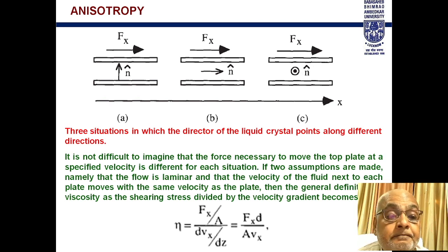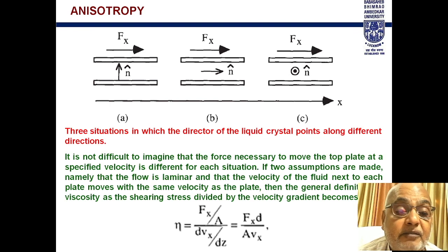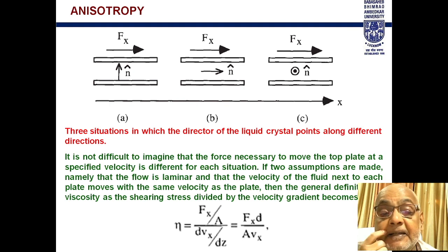and again it has the orientational direction. Three situations in which the director of the crystal points along different directions. It is not difficult to imagine the force necessary to move the top plate at a specific velocity is different for each situation. If two assumptions are made, namely that the flow is laminar and the velocity of the fluid next to each plate moves with the same velocity as the plate,